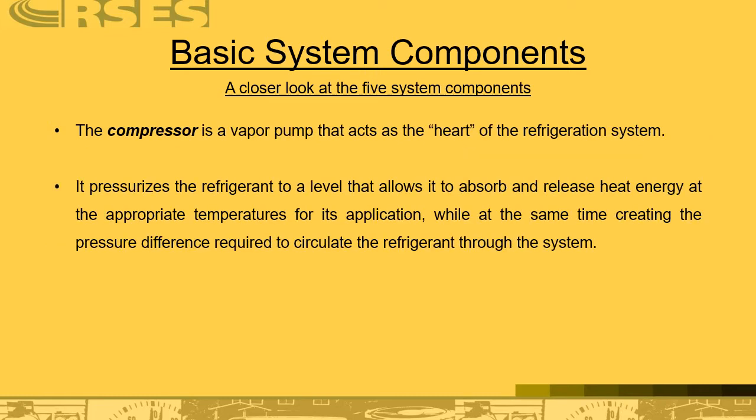The compressor is a vapor pump that acts as the heart of the refrigeration system. Without the pump, nothing happens. It pressurizes the refrigerant to a level that allows it to absorb and release heat energy at the appropriate temperatures for its application, while at the same time creating the pressure difference required to circulate the refrigerant through the system.